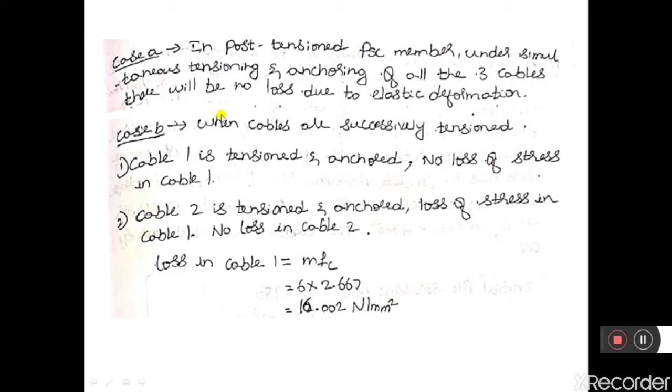First let us consider case A, that is, all the cables are pulled together. So the cables are simultaneously pulled. When all the cables are pulled together, the loss due to elastic deformation or loss due to elastic shortening will be 0.